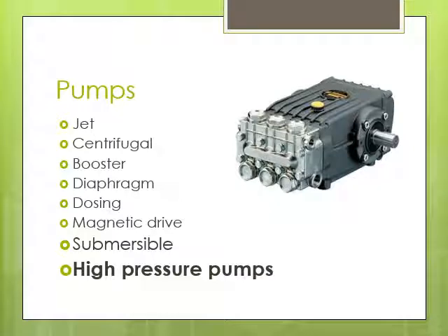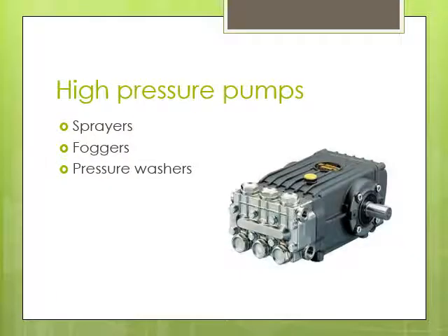Then there's high pressure pumps. You see these on pressure washers. Sprayers, typically in agriculture, that's what runs the chemicals through. Each one of these represents a piston, and this shaft sort of rotates and moves the pistons in and out, which creates pressure.